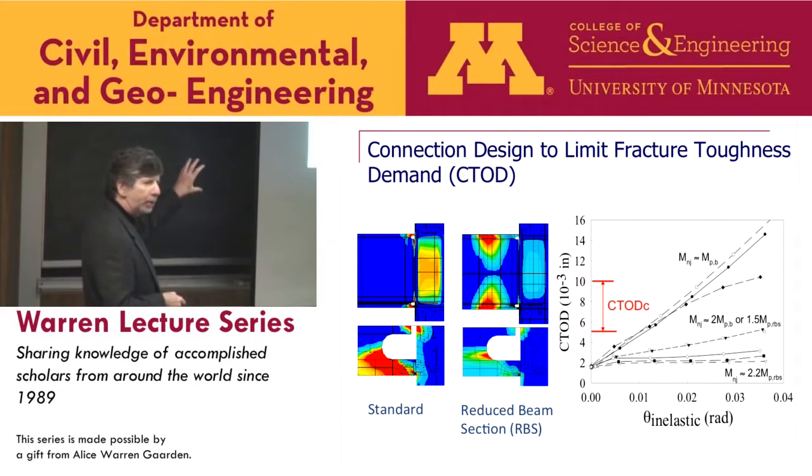And so we could build these computer models. We could look at the inelastic rotation that we would apply to these finite element models in the computer and look at the different crack tip opening displacement, the fracture demand, as a function of changes in design details. Again, I won't go through the details of what the design changes were, but this was an effective tool by which we could start to evaluate differences in design details, hone in on a design, and then do some laboratory validation testing.